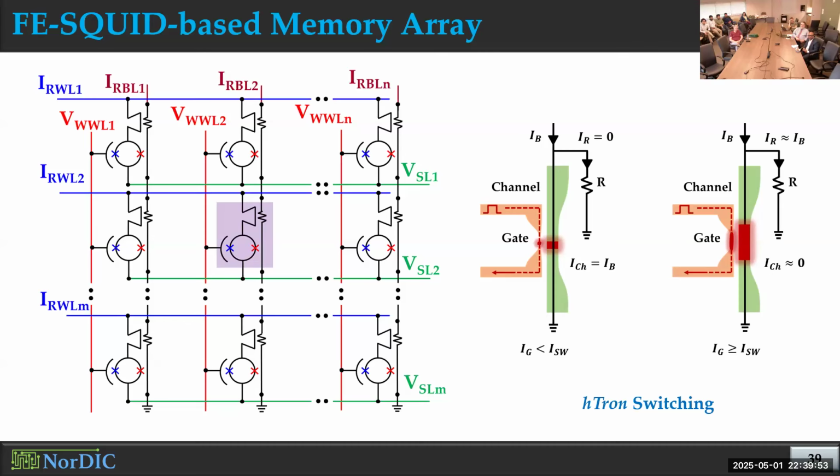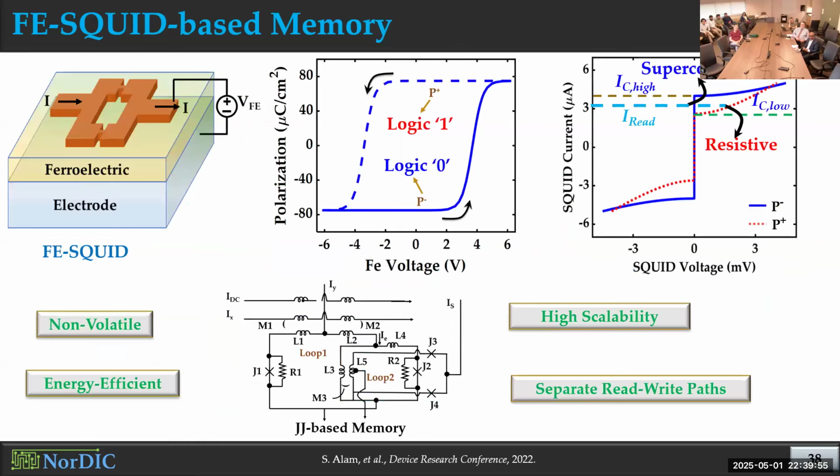Yeah, and also if you go to the previous slide. Yeah. And also the memory cell that you see, that's volatile. And the read operations are destructive here. So you'll have to do the write operations after each of the read operation. But in our case, the device is non-volatile and the read is non-destructive. So that's another advantage. Yes, ferroelectric is non-volatile. Yeah, that's storing the data.